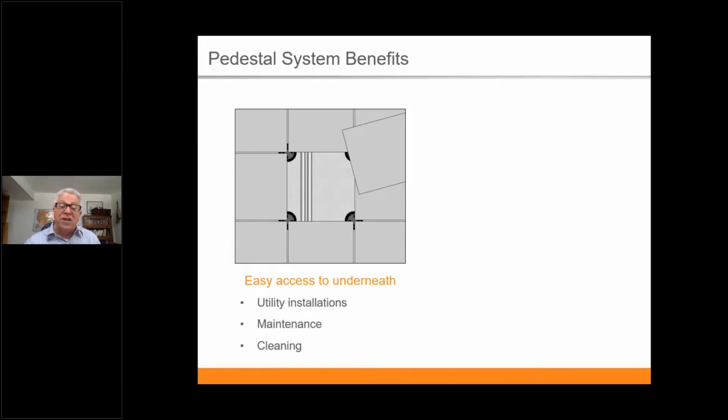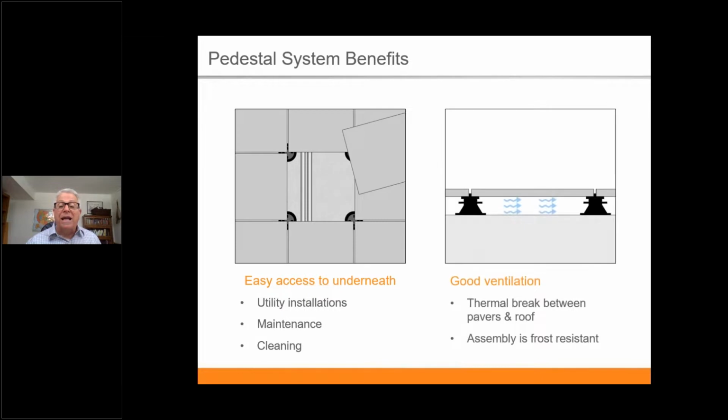It's also nice, as I said earlier, because you can actually do maintenance and cleaning. You can get to underneath there. You just lift up these fairly thick, heavy pavers and get to the underside, put them back in place. Also great ventilation, so you don't get the heat, you don't get the cold. You can have that area in there as an air gap. So keep those in mind.